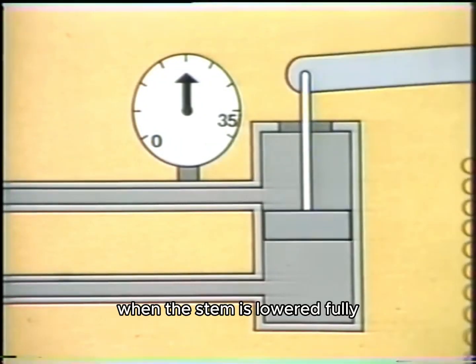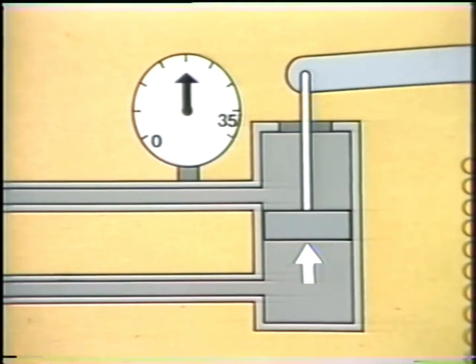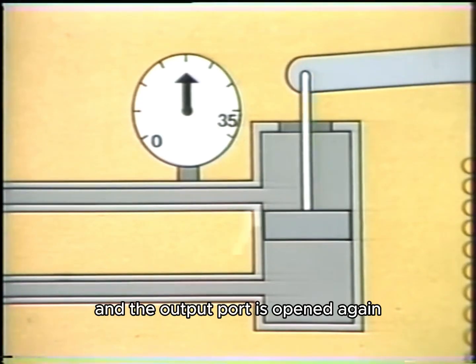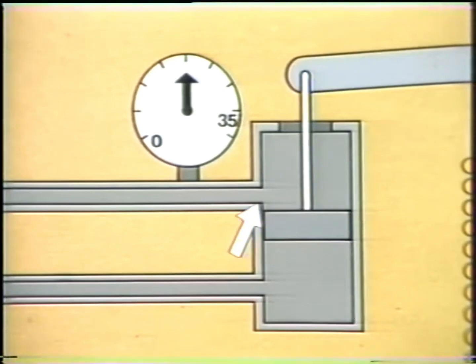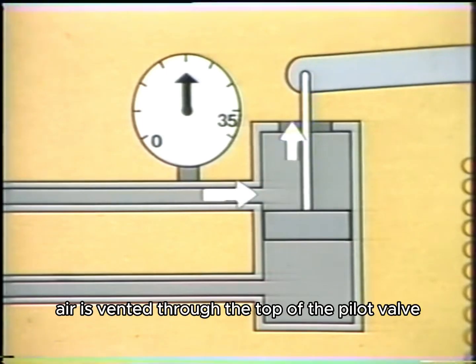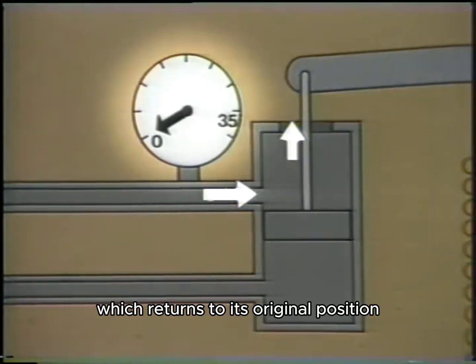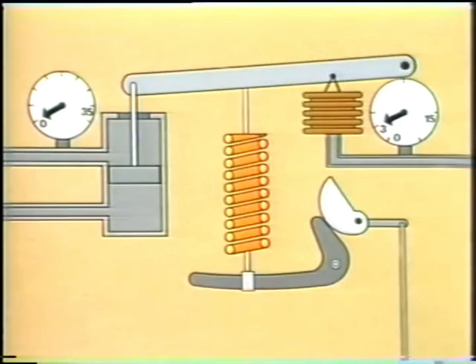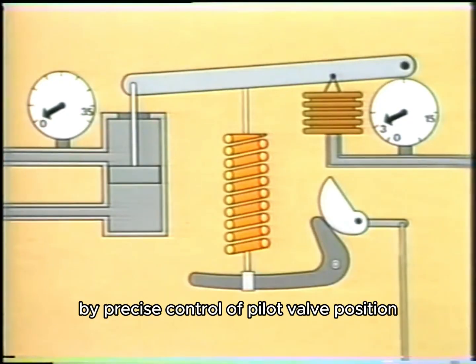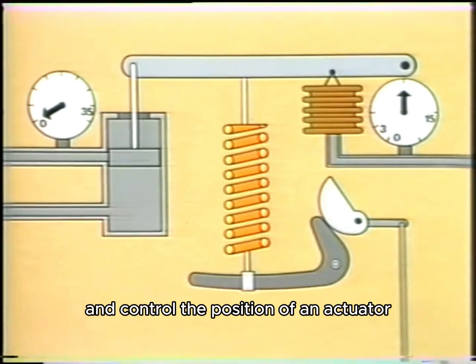When the stem is lowered fully, the air supply is closed off, and the output port is opened again. But this time, the trapped pressure is released. Air is vented through the top of the pilot valve, relieving the pressure on the actuator, which returns to its original position. By precise control of pilot valve position, we can accurately regulate the pressure and control the position of an actuator.